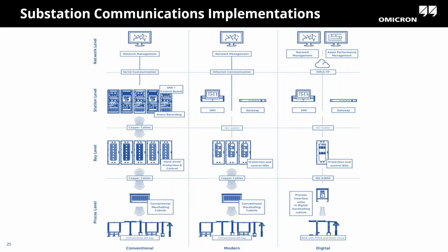So that's where the advent comes in, all the way on the right-hand side, of a true digital substation, where any of your devices are actually able to see all of the data representing your entire power system. Here we can see that the primary equipment basically stayed the same, and what's changed is that the data from the primary equipment is digitized outside of the control house. So by the time it gets to the control house, you can use just a single communication cable or redundant communications, and then any device can basically see any of that data.